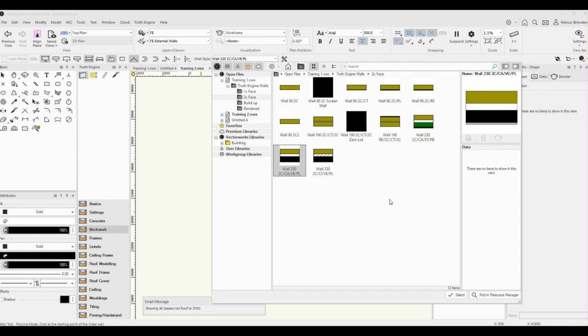So if you look at some of these other wall types, we have one here which is very similar. The only difference is the cavity is now CI, which stands for cavity insulation. So if you want to take quantities for insulation, you would use this wall instead. So just other types here as well, like a stock standard two course face with no finishes either side. We have, for example, here two course face with plaster on one side, and that's used in the case where you have a two course face wall, one side's into the garage, the other side's of the house.